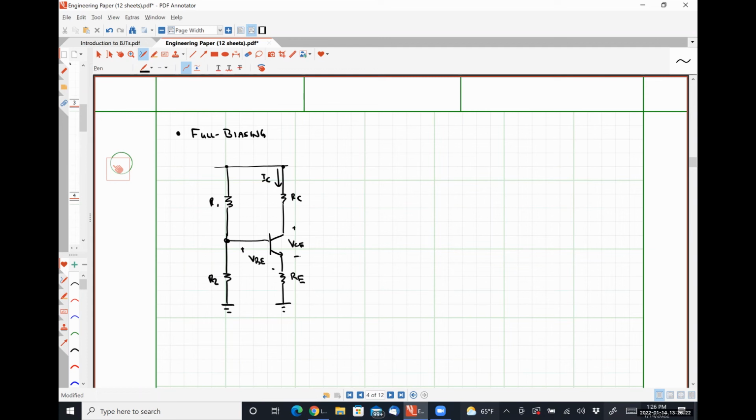Now it's smaller because of that resistor biasing network, right? So if VCC changes by 5%, Vthevenin is going to change by a value that's less than 5% because of that network, right? But there's still going to be some small perturbation, which can lead to a reasonable change in the collector current. What this emitter resistance does is effectively lets the quantity VCE and VBE float a little bit. So this resistor serves to absorb some of the perturbation and minimize its effects, okay?